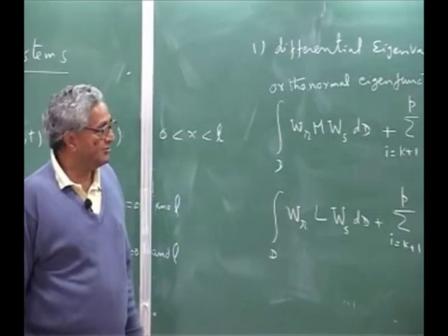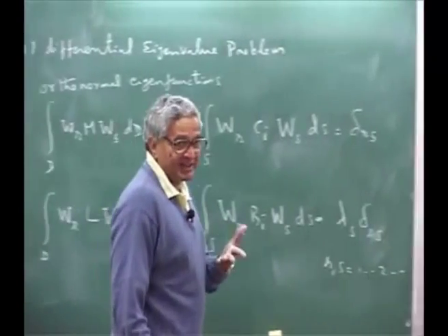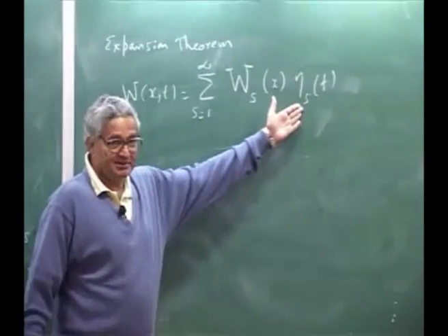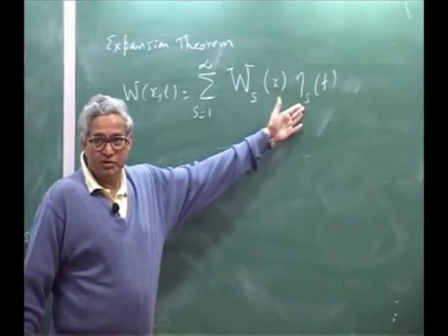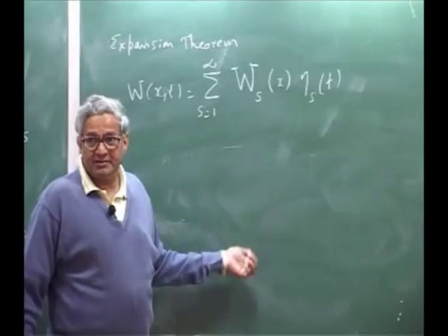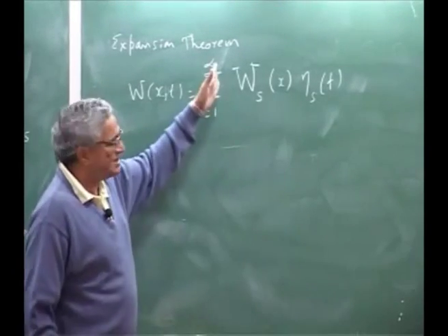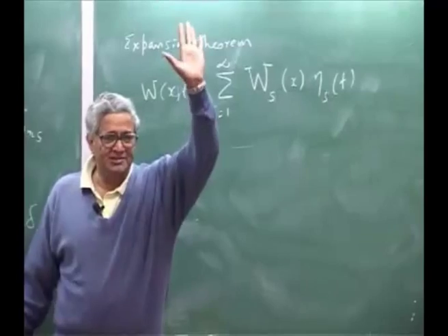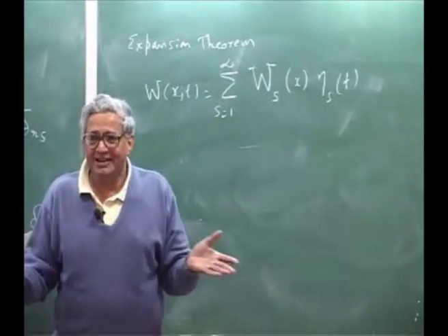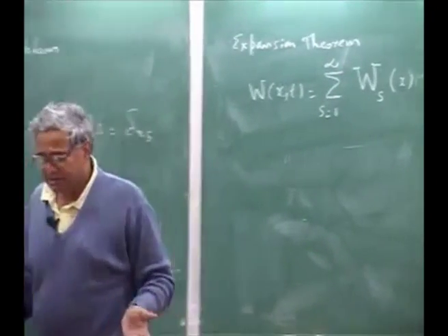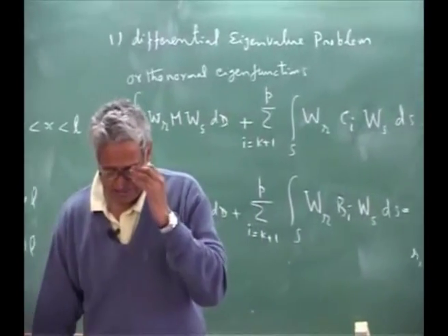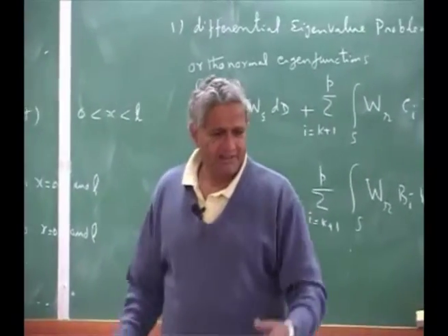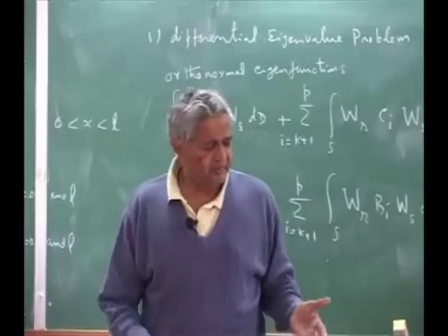How many unknowns, how many generalized coordinates do I have? I have infinite, and you know that I have infinite eigenfunctions. But I will not really solve for an infinite number of equations. I will set it to a finite number. Usually in vibration problems, sometimes people take about 7 modes, 8 modes.